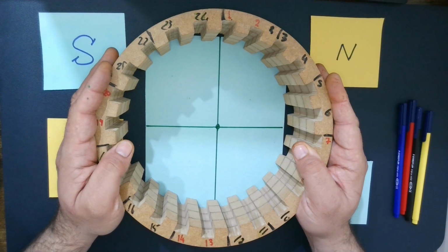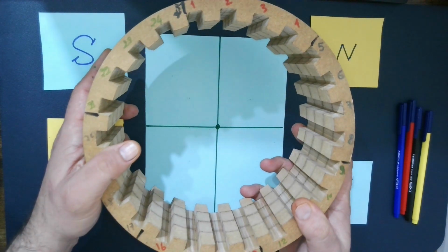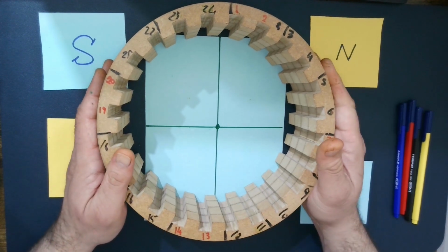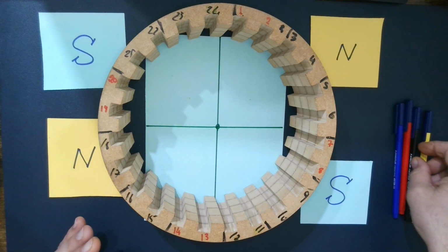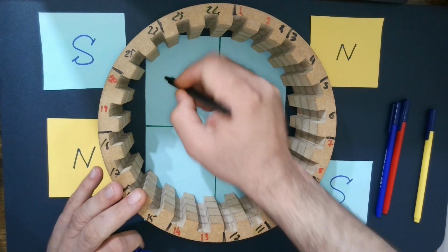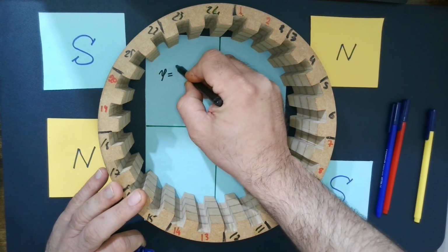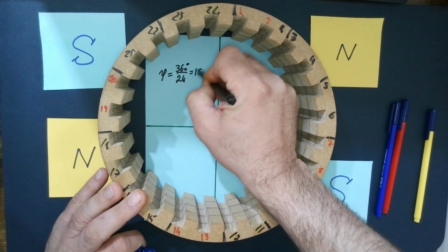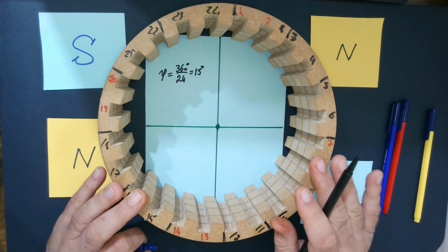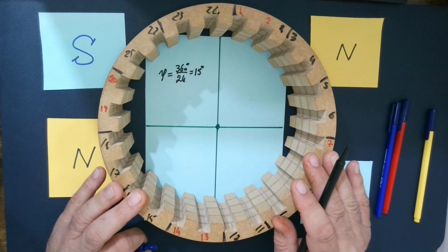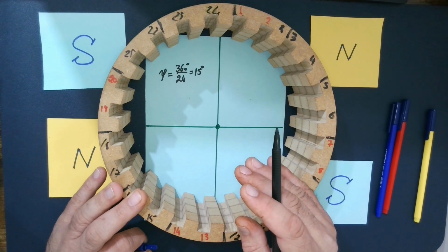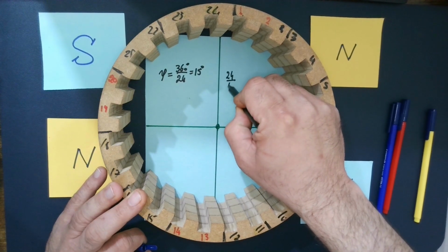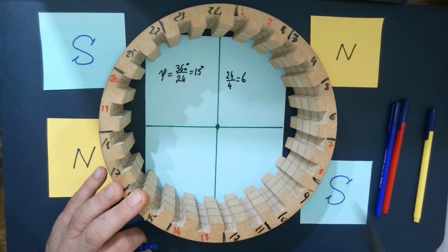This is the model we used before for the 2-pole machine. This side, 24 slots for 2-pole machine. So I'm going to use this side for 24 slots 4-pole machine. So we have here 24 slots. So the slot angle psi will be 360 degrees divided by 24. That one will be 15 degrees. Same like 2-pole machine. But how many slots per pole? In the 2-pole machine, we have 24 over 2 give you 12. Here we have 24 divided by 4 give you 6 slots per pole.